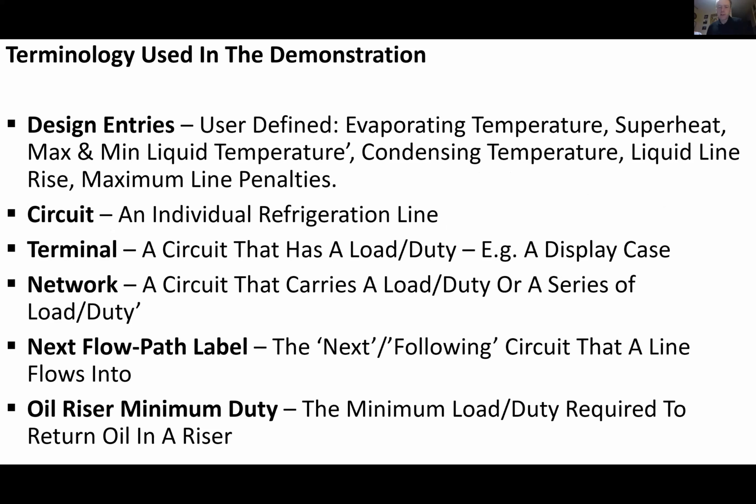So I want to talk a little bit now about terminology. MicroPipe's got its own terminology. If I speak to a design engineer within the UK who uses MicroPipe: design entries, circuit, terminal, network, next flow path label, oil riser, minimum duty. We're all familiar with it, but it might be an unknown terminology to some of the audience this evening. But specifically, design entries, these are user defined.